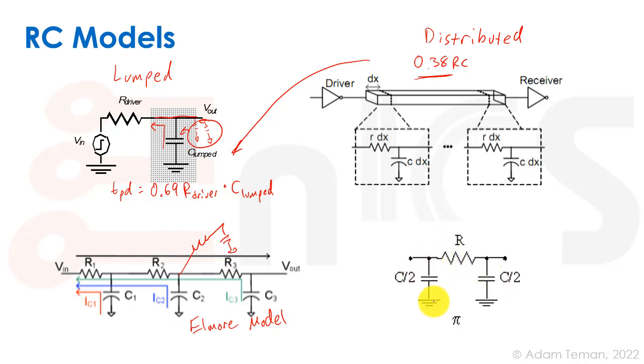When we go to simulation, how do we break down a line so it will be distributed? Because if we take this and we lump everything together, or even don't take any of the capacitance of the wire, we're going to get a really bad estimation in pre-layout simulation. So only during post-layout can we have a well defined type of broken down wire that's going to show the different pieces of the R and C, and then we can take that into consideration in simulation. But for pre-layout, we should always use one of these models, like the pi model or the T model, and depending on how much you want the accuracy versus the trade-off of the calculation time, it can be a pi or a 2 pi or a 3 pi or 4 pi and so forth.